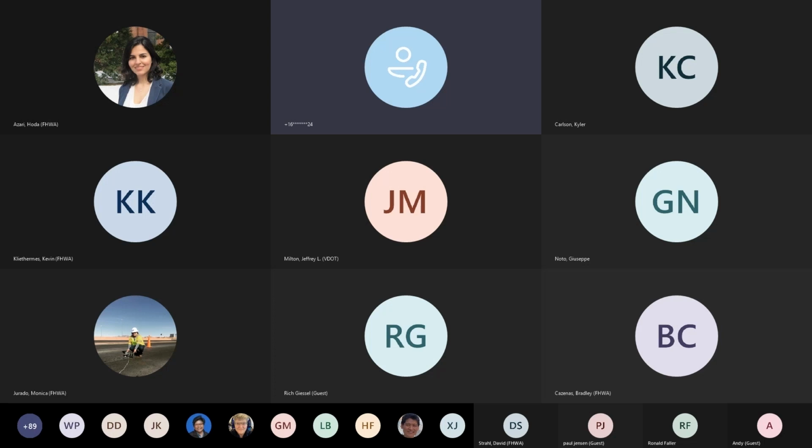And it also, if you talk about waterborne preservatives in glue lam members, that's where the laminations are glued up into very large beams, it can promote checking, and in some cases, excessive checking in service. And so those are some concerns. So if at all possible, we still recommend an oil-type preservative. One that is very favorably reviewed by EPA and their regulations is the copper naphthenate. And so that would be a good option.